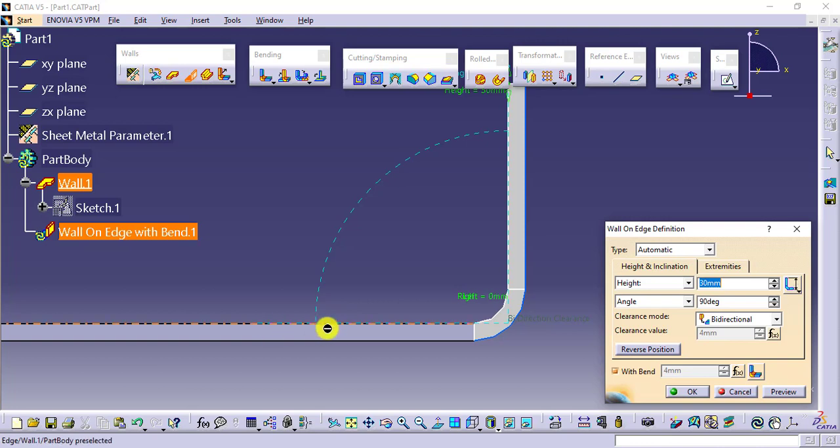If this particular base is 100 mm, then till this level it will be 104 mm, and till outside it will be 106 mm. So yes, whenever we create the sheet metal entities, we need to focus on these dimensions as well. Otherwise there would be either some extra dimensions or some less dimensions if we do not focus on this particular clearance mode.